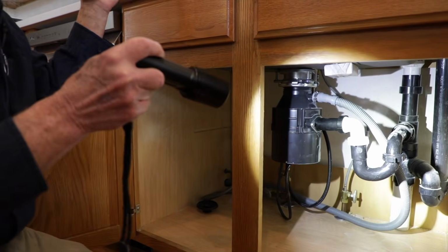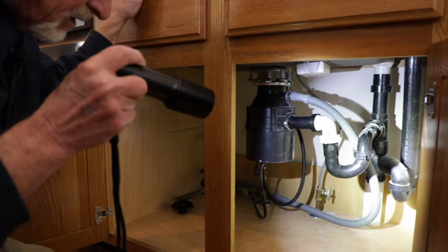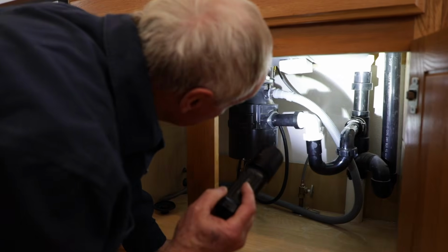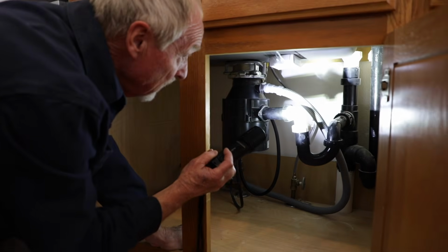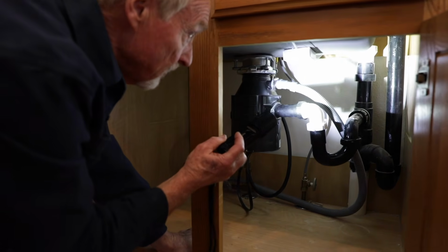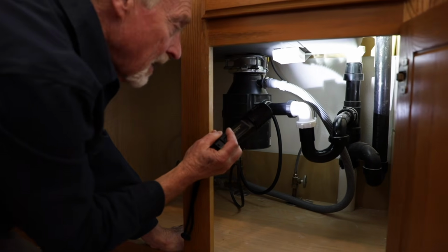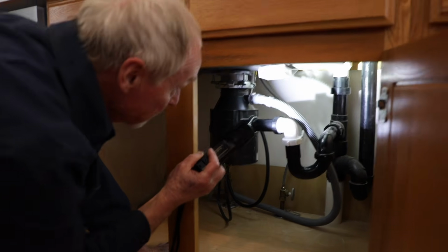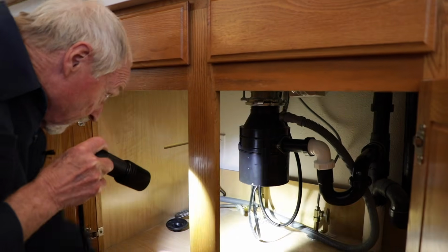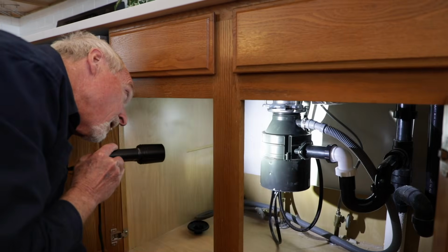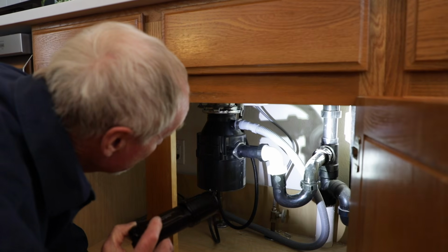So sometimes it takes a little essay to explain this stuff in our reports, and I see an essay in the future here. Also, just for interest here, we have an air admittance valve on the plumbing vent here so it doesn't have to vent to the outside of the house. That's that white gadget at the top there, AAV, air admittance valve, and that's looking good, so no problems with that. So otherwise, except for our issues with the dishwasher discharge, there is no problem here.